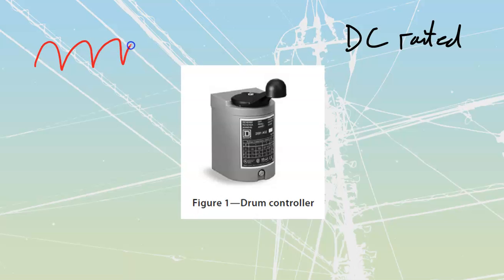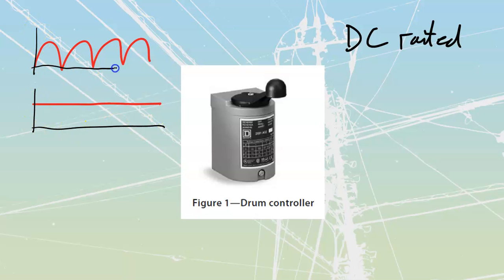DC can look like this, where it's going to be pulsating DC. DC can also look like this, where it is going to be a continuous high value of DC, rather than this pulsating one. This one would be a rectified. This other one down here is going to be a rectified and filtered and basically trimmed type of DC, where I'm going to have a unified DC.